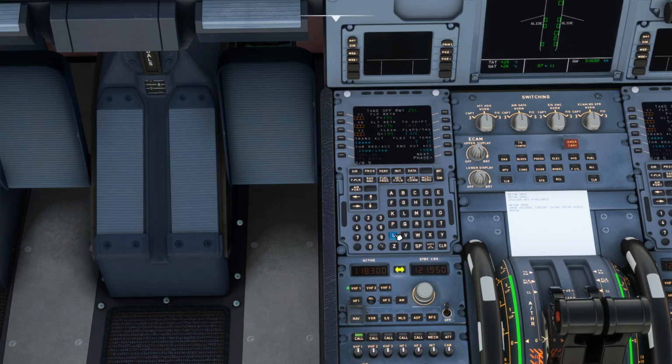You're not going down. So it's 2/0.5 up. Okay, so this is up. This is a format that you should learn. You can keep flaps 1, 2, 3. 1 or 2 is good, and then slash up 0.5, and that's it. You need the flaps. And flex to temperature.